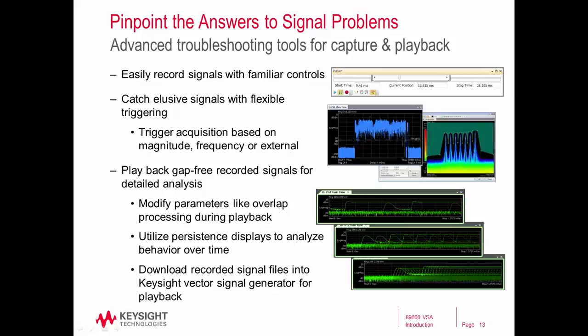There's a player that can be used to easily record and then play back these signals. There's also triggering, which you can set up to define when you would like to start the acquisition, and this can be very helpful to catch elusive signals or to make sure you catch the event that you would like to analyze.